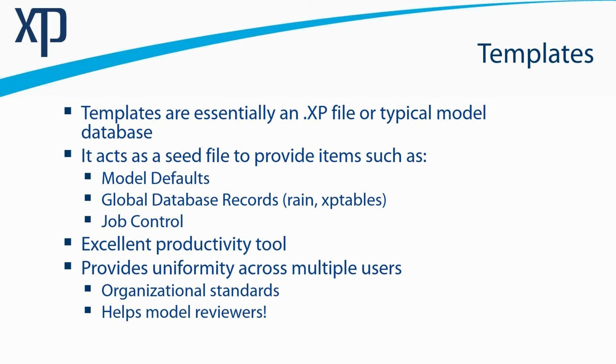It can provide some uniformity amongst many users. So you've got several people that are going to be using XP. If everybody starts with the same template, then you can embed into this template all your organizational standards. Let's say you have a special drawing format in CAD or GIS for a catchment polygon or for a land use of buildings. Well, that can be duplicated in the template, and then whoever is doing XP modeling starts with the template. Everything's all uniform, and as a reviewer, let's say, you have the same expectation all of the time as you get models, and it's not going to be hard for you to review because everybody started from the same base.